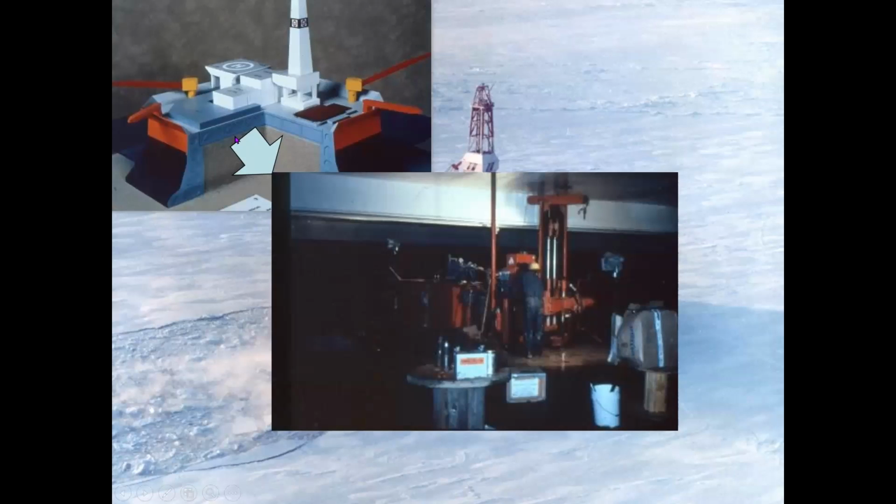And you look there, you see a bit of space. Well, this slide here shows us working in that space. There's about 3.5, that's the sandfill. So that's the sandfill core. The guys are standing on the sandfill core. That there is the underside of the steel girder box deck. And we're cone testing. And we did a lot of cone testing.